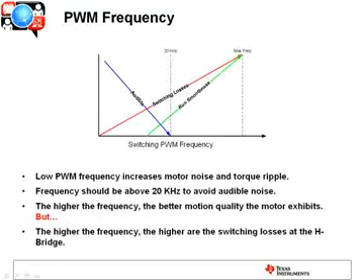So in terms of the PWM frequency, there's a couple trade-offs here. The first is, in an ideal world, you want to get the PWM frequency out of the audible range. And that's simple enough in terms of the reason you want to do that is if it's in the audible range, you can hear that. And you can see this in some of the legacy motors that are using the switching frequency where they're, say, 15 to 16 kilohertz. You can actually hear the switching frequency of that motor.